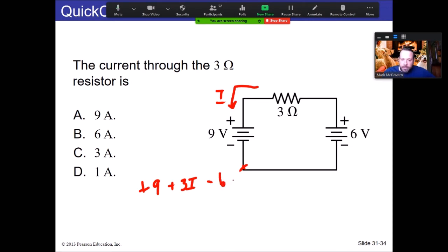And if I solve for I, you get negative 1 amps. So what that is, that's science telling you, yeah, you can make your own decisions, but you're wrong. Okay, we were wrong. The current does not go counterclockwise, it goes clockwise. Now, what would this mean if you're solving this problem here? You don't have to redo the problem.